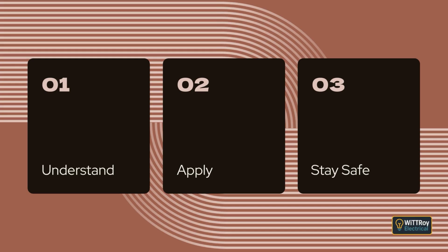Clause 2.2 Arrangement of electrical installation. Clause 2.2.1 Circuits. Clause 2.2.1.1 General. This clause tells us that an installation must be divided into circuits in a sensible way. We think about how equipment operates, how much current it draws, and what needs to stay reliable. Circuits should be arranged so a fault on one part does not shut down large areas unnecessarily. Lighting, power, heating, motors, and safety services should each be placed on circuits that make sense for their function. Safety service circuits must always be kept separate from normal circuits so they stay active during emergencies.